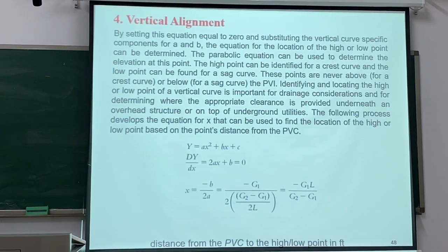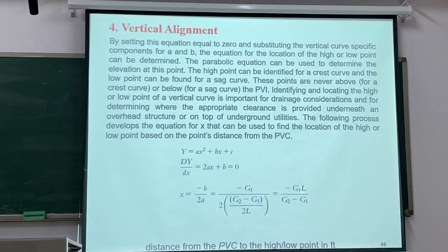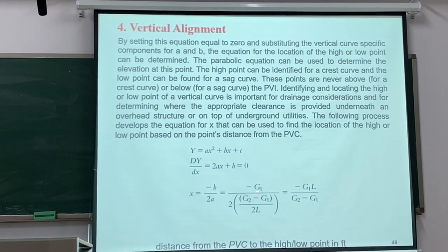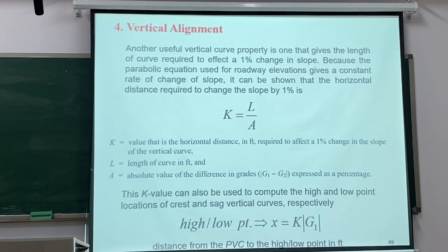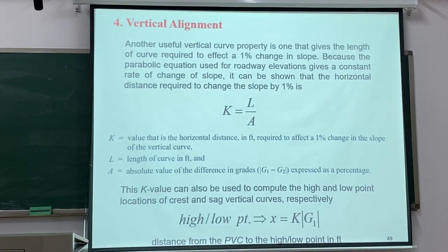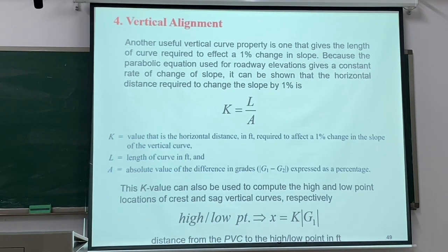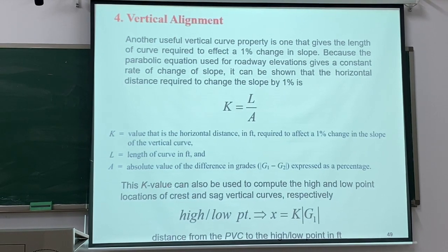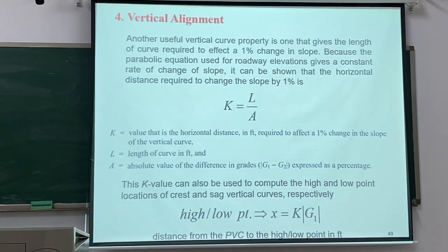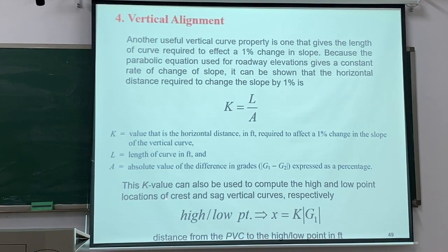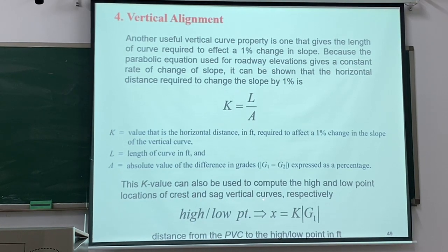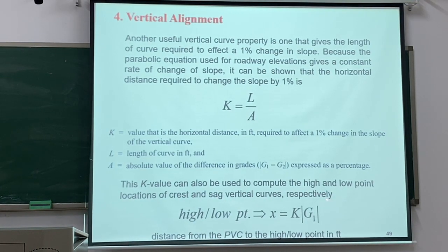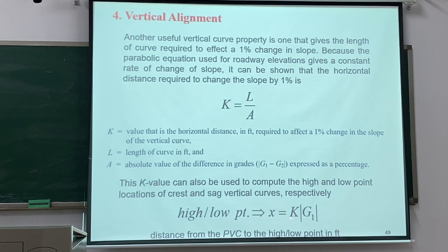So we should compare this equation and this equation. The K value can also be used to compute the high and low point locations of crest and sag vertical curves, respectively, like this.